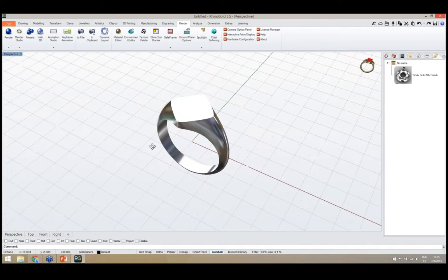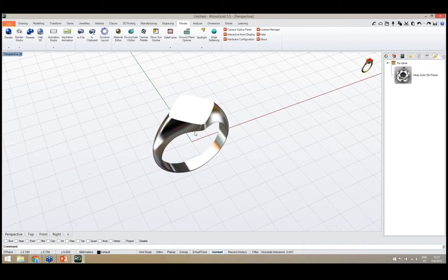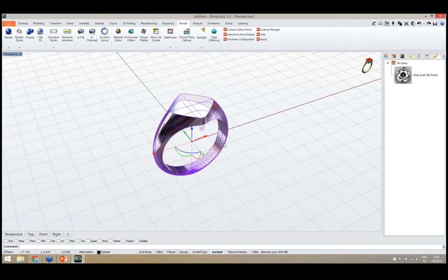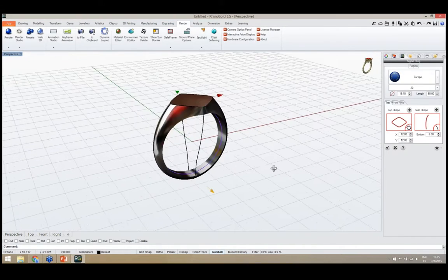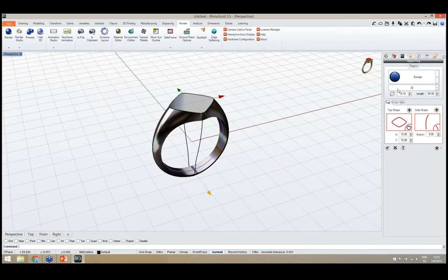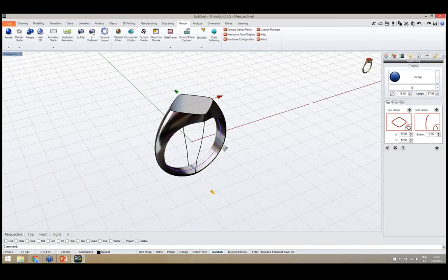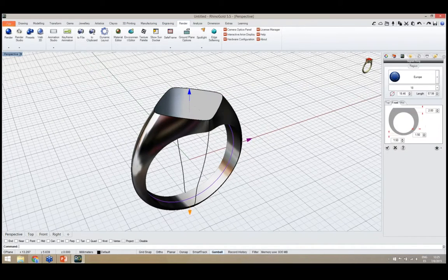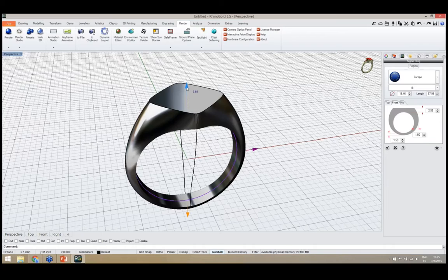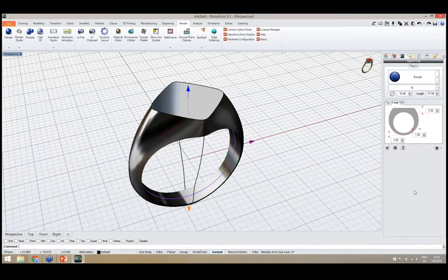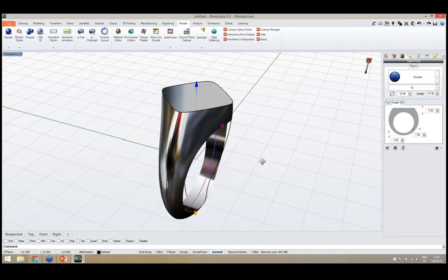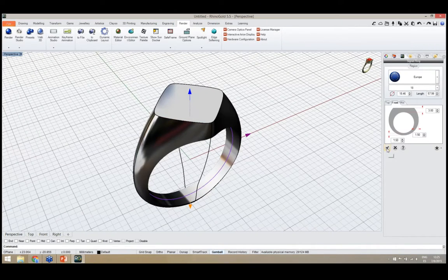And now we have the signet ring defined, but I want to adjust any parameter. So as always, we just need to select the model, edit, and in here in the side panel we can adjust anything we need. So we can define a new ring size, we can define the 8, for instance. I want a little bit bigger in here, so easily I can define 3 millimeters, for instance. So it's really easy to customize exactly as we need. After this, I just click OK.